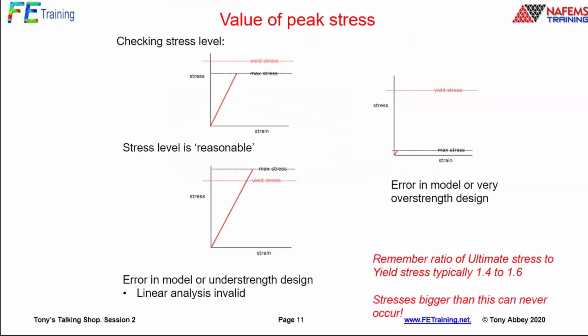The reason for asking this is, if it's a linear analysis, and the biggest stress in the model is at this value, then we're below yield, and that's okay. Again, we're not getting into the actual detail. We're not doing a verification mathematically to say this stress looks okay from an equilibrium point of view and so on. We're just using our knowledge of the material in this particular case to say it's a linear analysis.